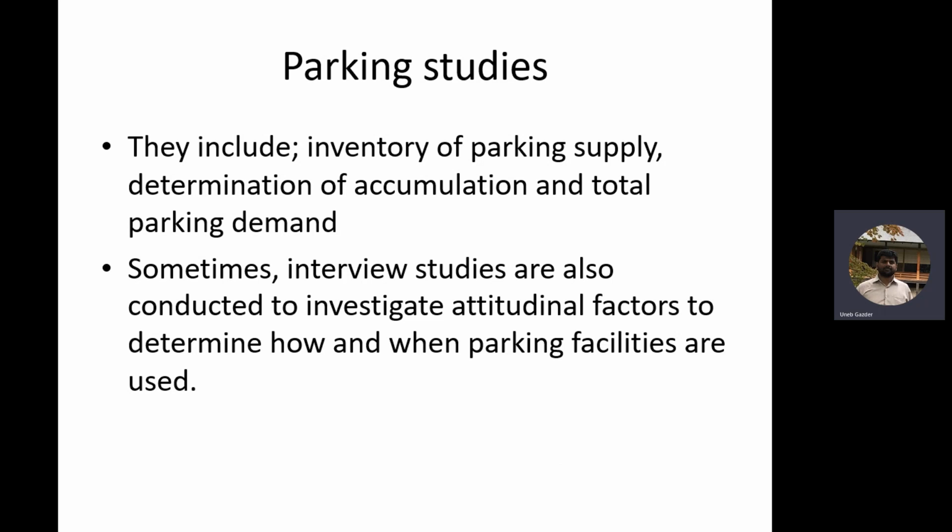Duration, you know, right? So it's the average duration. All of us don't park for the same time, right? Our duration is different. I come for the whole day, you come for half an hour and so on, right? So parking duration, average parking duration. And accumulation is number of vehicles at a given time which are occupying the parking area. Okay, accumulation of vehicles at a given time.